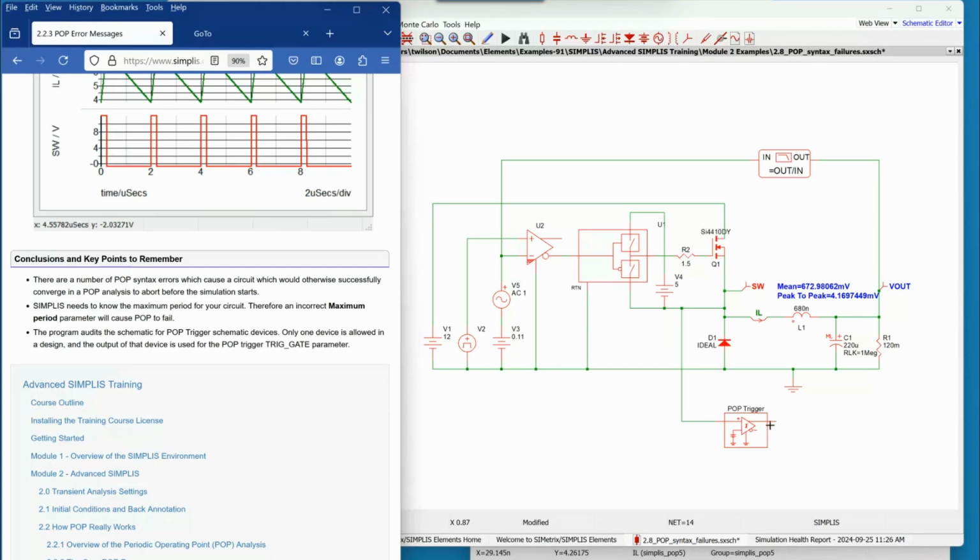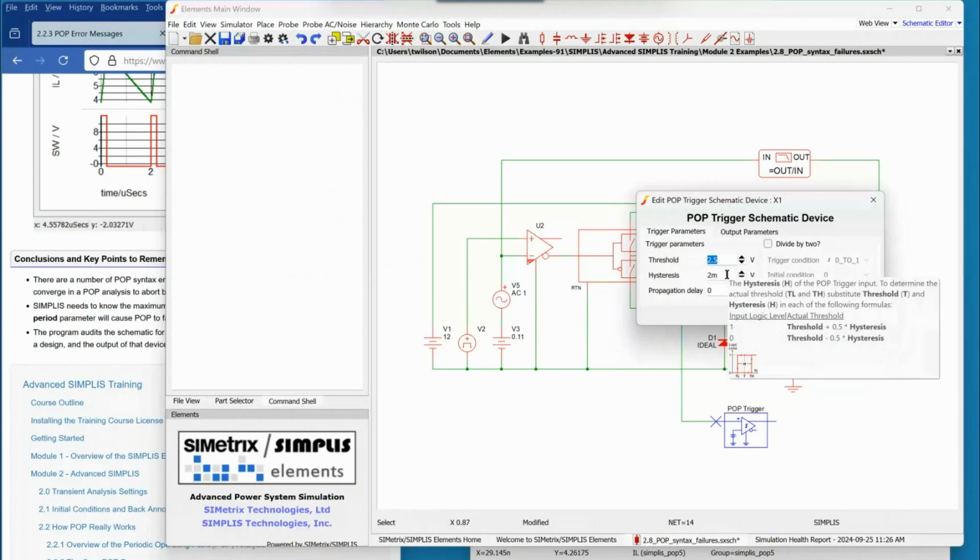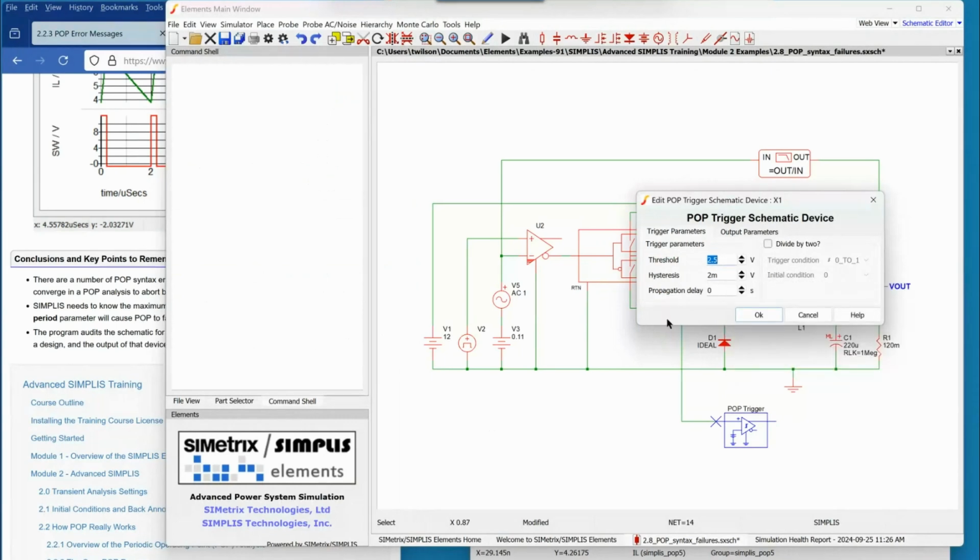So you have control. I usually make that hysteresis large because it's typically a large transition, a large signal event. So all I care about is it hits some peak value and it goes to 0 or goes to some low value. Right. So the large hysteresis gives you more noise immunity. That's a good point. Right.